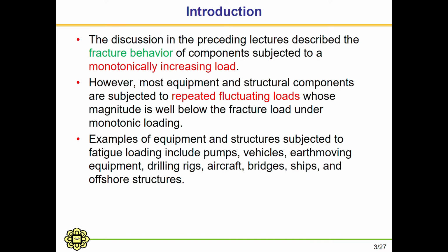So, for the introduction, the discussion in the preceding lectures described the fracture behavior of components subjected to a monotonically increasing load. However, most equipment and structural components are subjected to repeated fluctuating loads whose magnitude is well below the fracture load under monotonic loading. Examples of equipment and structures subjected to fatigue loading include pumps, vehicles, earth-moving equipment, drilling rigs, aircraft, bridges, ships, and offshore equipment or offshore structures.